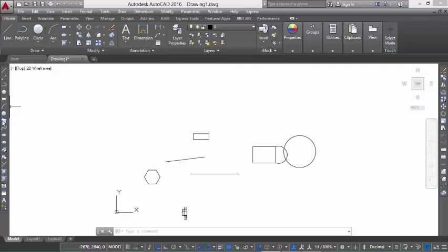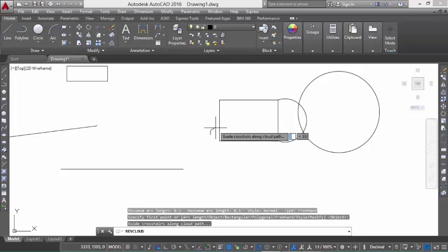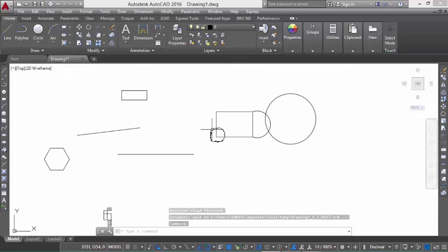So next in line is the revision cloud. If I want to identify a hidden area, I just click draw. As I move my mouse, I'm not dragging it, I'm just moving it so it joins. When I'm done, I just click to join it. You see, automatic.